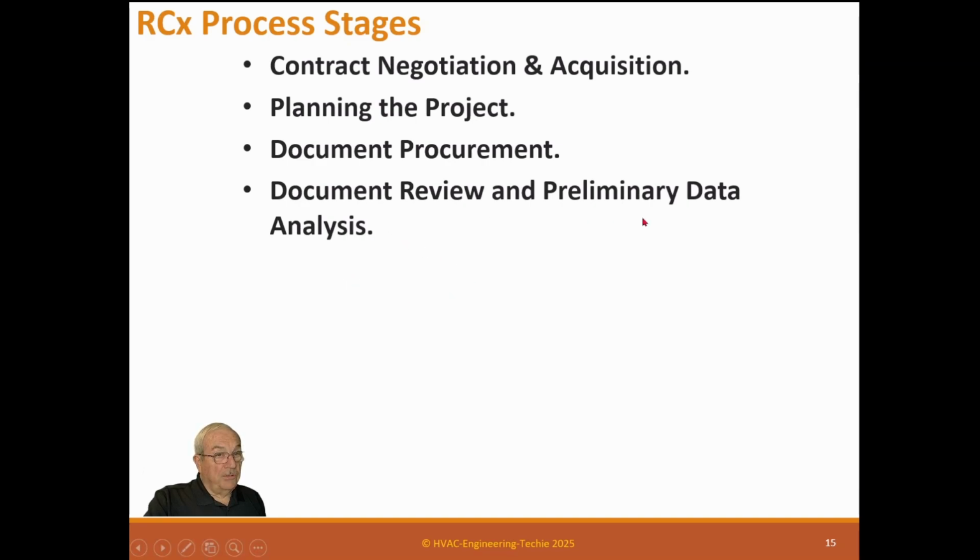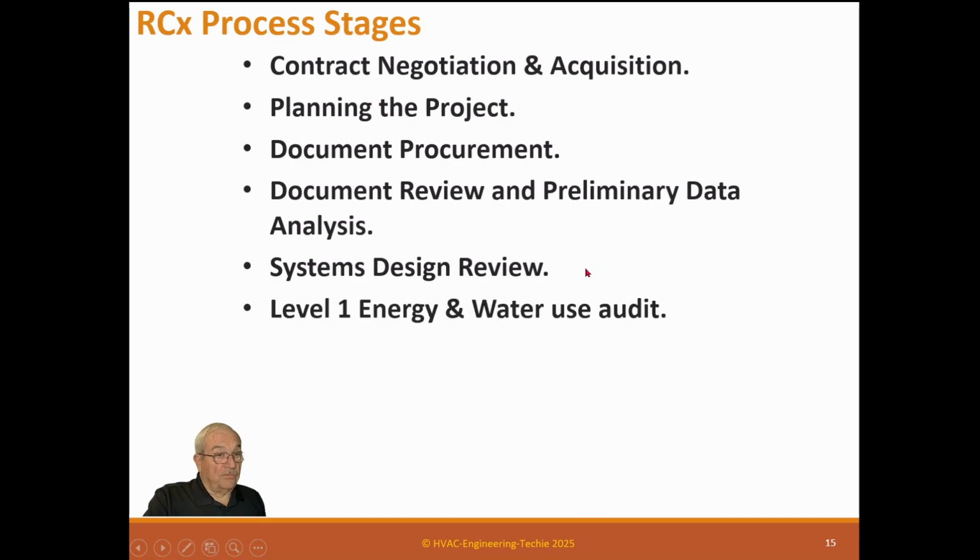You need to review and do a design analysis on these documents, and you need to see, did they actually buy the right equipment? Is it the right size? You've got to look at all the submittals. You've got to look at all that stuff. You do the system design review. It doesn't have to be a real deep design review, but you're trying to find the problems on paper before you actually go to the field to look for them.